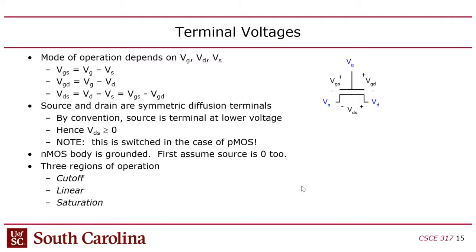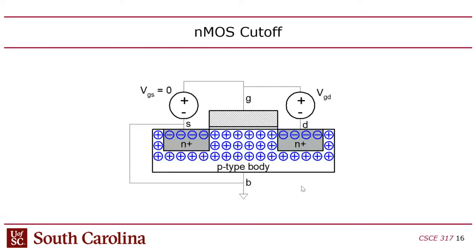I mean, at least I wondered that. I'm like, well, how do I make, like, where do I buy a current source, right? Because if I get a battery, that's a voltage source, right? Well, this is an example of how you would make a current source: if you saturate one of these MOSFET transistors, it ends up providing a fixed amount of current. Okay, so let's look a little bit more closely at how that works.